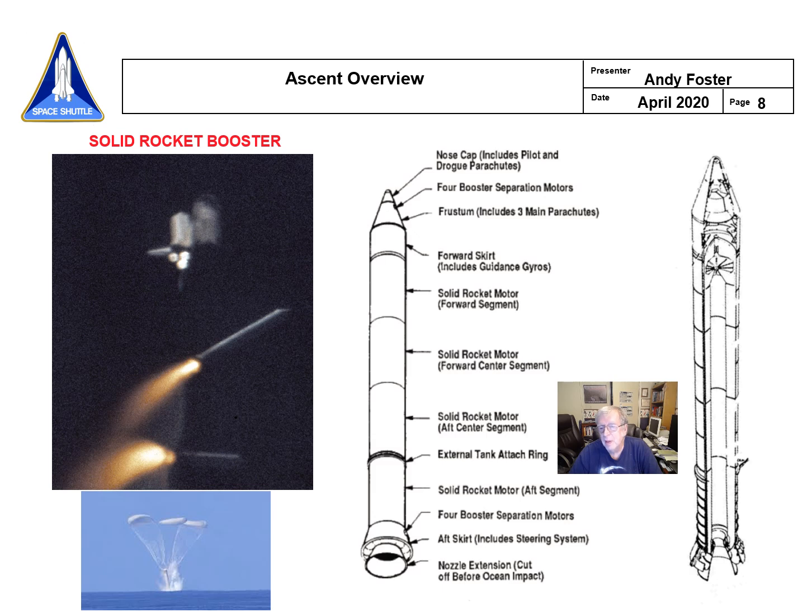So when you light one of these off, it burns the entire length and it burns outside in. The shape of that cavity can be used to actually control the burn rate, which essentially controls the thrust that the solid puts out. And we actually did tailor the thrust down a little bit when we're going through maximum dynamic pressure, which I'll explain in a few minutes.